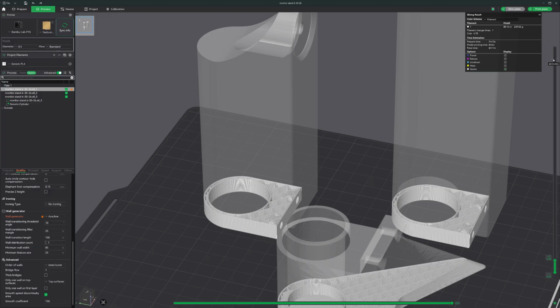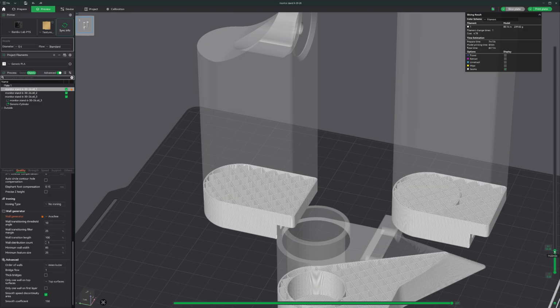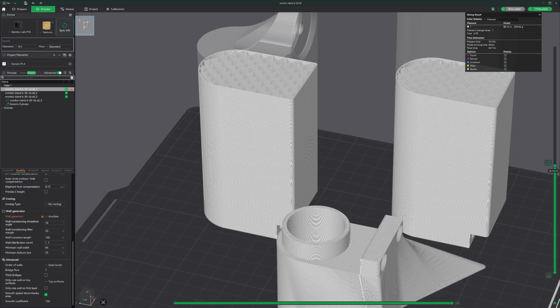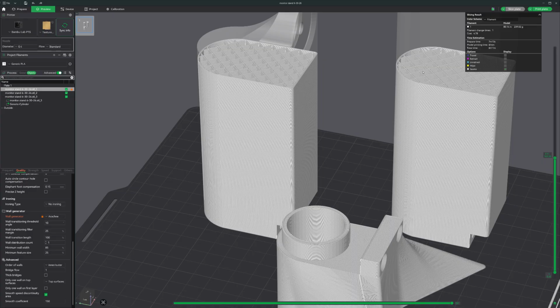Also, anytime you need to manipulate this in order to see what layer you're working on, notice this bottom number right here. It tells you what layer it is and the layer height. Knowing that, if you start to have a problem with a print at a certain layer height, you can actually measure it out using a ruler or a pair of calipers, and then come back in the slicer and change some other settings at that layer height using a modifier. This is exactly what we're going to be doing here, but for making a part stronger. You can also use it if you're having issues at a certain height in your part, by being able to manipulate other settings in just that section.